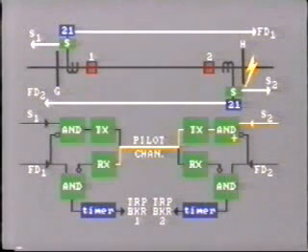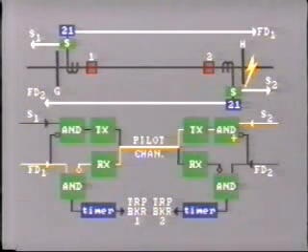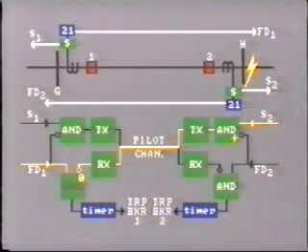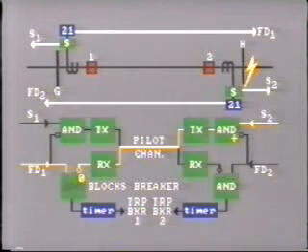This is received at the other end, station G, and the signal is passed into the permissive tripping circuit and mixed with the signal from fault detector 1, which, as you remember, is trying to trip breaker 1. The positive input signal from the receiver becomes a 0 signal. As this logic box shows AND, it needs 2 positive input signals, one from the fault detector and one from the receiver. But at this moment, it has only one, that from the fault detector. So the breaker is blocked from tripping by the transmitted signal.